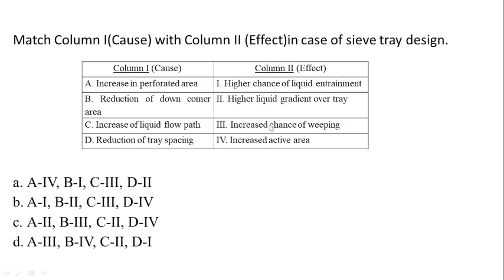If the difference in liquid height at the inlet and exit of the tray is high, then there are two options of tray. Either we can use split flow tray or stepped tray. So the answer will be option C, both split flow tray and stepped tray.